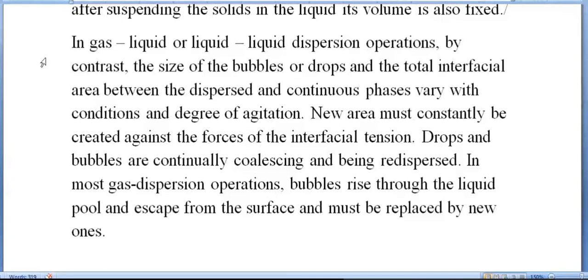Now you give connection to the cylinders, nitrogen cylinders. Then open the valve. Unfortunately, you open in such a manner that from the distributor plate also a jet of liquid is going out, a jet of stream is going out. Means what? The flow rate is very high, the velocity is very high. Now you slowly reduce the valve.